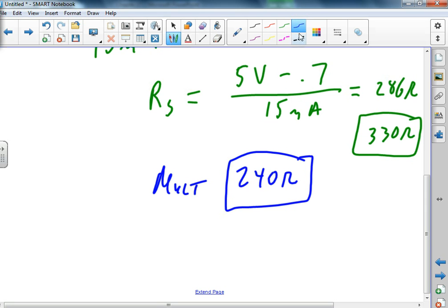And I'm going to do this one more time because obviously I didn't want a 0.7 there. I wanted a 1.7, right? 1.4. Yeah, that'd be better. So I'm going to do it one more time. 5 minus 1.4 divided by 0.015. And I come up with 240 ohms.